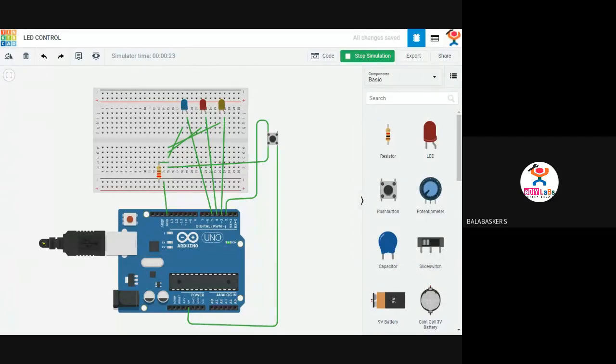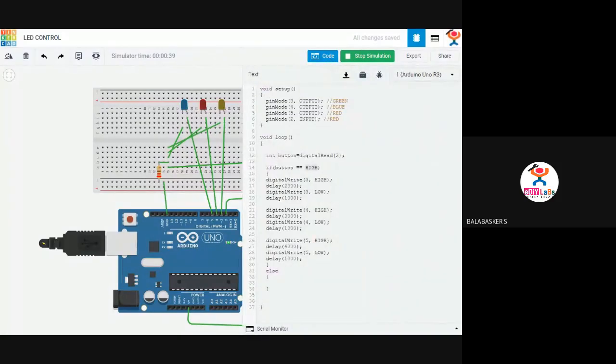It waits. So again what I should do? I should click that button. If I click the button one time, it will do the task. Even if I press it n number of times at a time, it will finish the task, and only then will it do the task again. Okay, this is the concept of the switch. In the switch, what I have used is digitalRead. As I'm going to read here, I have given this pin as an input pin. Are you clear?